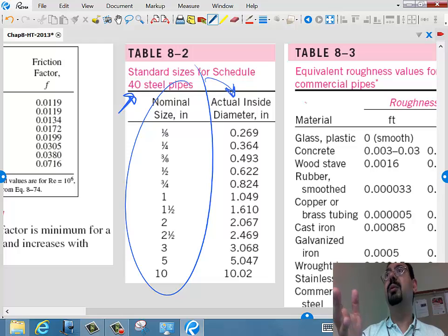So if it ends up exploding in the river, you'll lose a lot of money paying for compensation and cleaning, so you have to protect against explosion inside the river. So the bigger the pipe, the more expensive, right? The smaller the pipe, it will be cheaper, but what will go up? The pumping cost, right? You are not paying for the pipe up front, but you'll keep paying for the pumping work over the life of the project. Because of the friction loss, you'll have to spend a lot on the pumps.